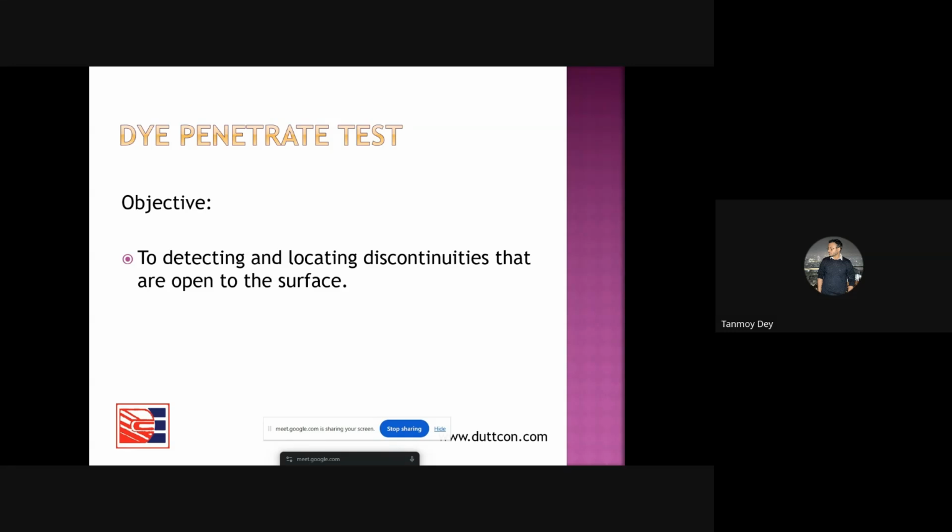What is happening? If you have multi-run welding, after getting the full welding, if you go on testing, the entire thing is lost. So what is suggested, during every run, or every 2 to 3 runs, one dye penetrant test is done, to see whether there is any crack or not. This dye penetrant test is done for detecting surface cracks, only surface cracks. The principle is very simple. It is the surface tension.